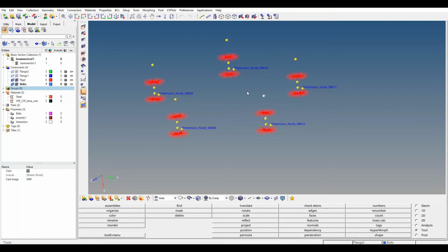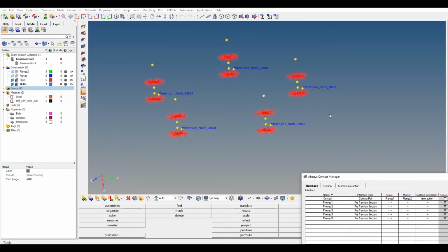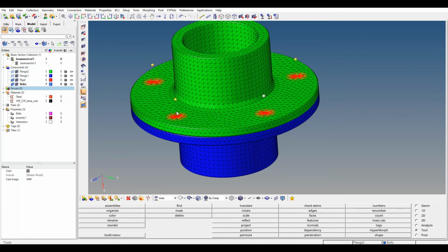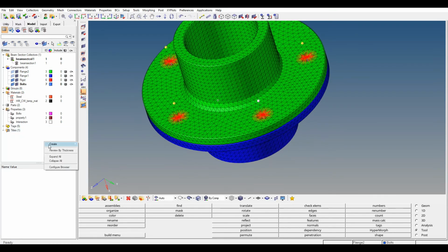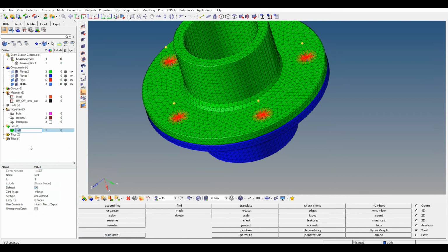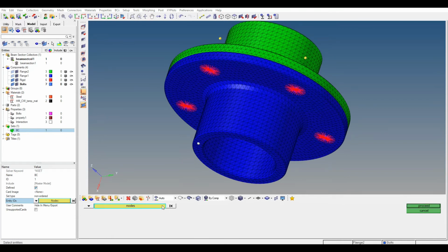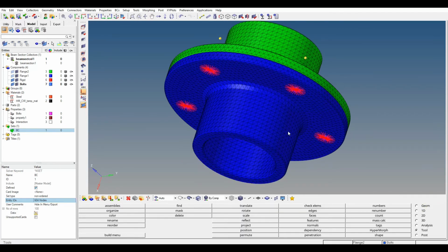So now what I'm going to do is just close this dialog, okay, and create the sets to apply the boundary condition. So we will clamp this end. So just select these nodes. Okay, and now I'm going to create another set called preloading nodes.